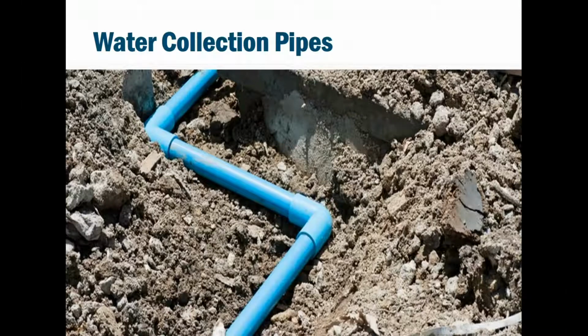If your native subgrade has poor infiltration, or if you're required to direct the water to a central location, collection pipes can be installed in the open graded or engineered filled base courses. The pipes can have perforations to collect the water and be sloped to maintain velocity without affecting your surface grade.